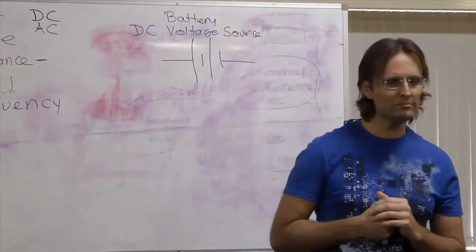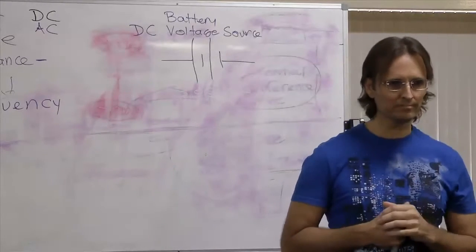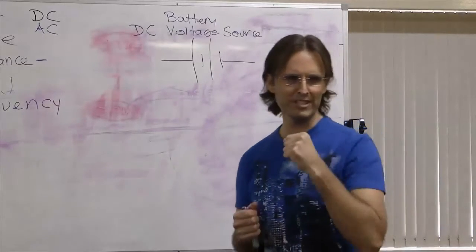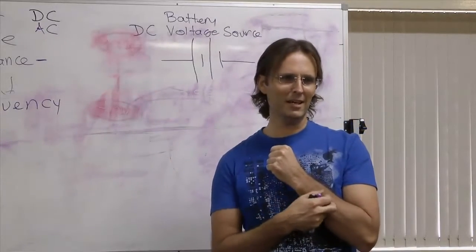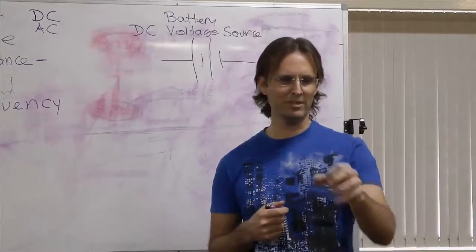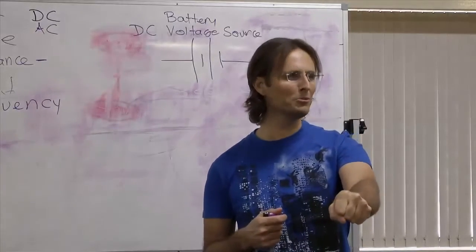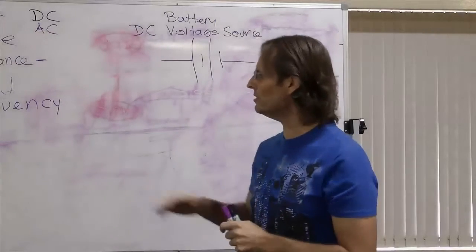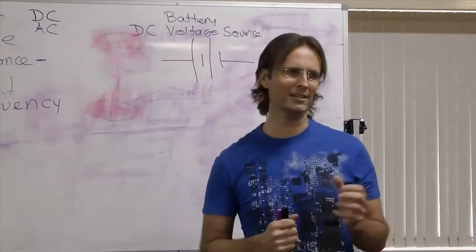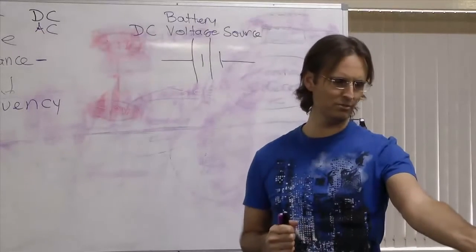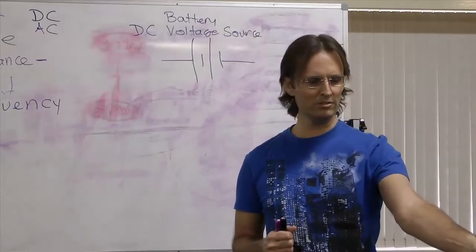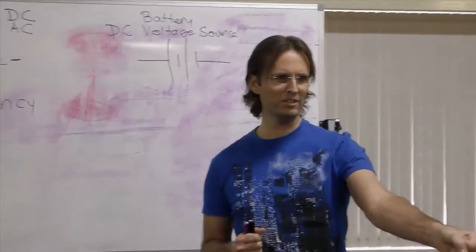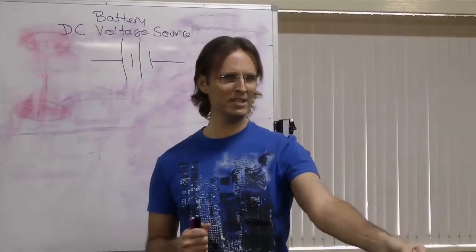With respect to electric shock, time plays an effect too. The longer the shock, the more dangerous it is. Of course. So if you just briefly touch something, that might have a certain effect, but if you hold on to it, obviously that's going to have a completely different effect. And there are also problems with alternating current. If you grab hold of something that has alternating current, your body goes into a convulsion, which means you can't pull yourself away from it very easily.